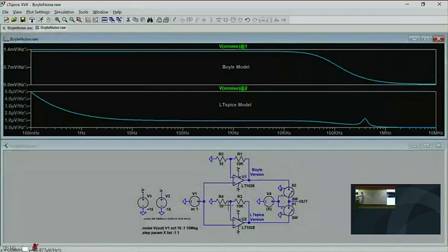So this common mode current is read out to voltage with these things. Now, if Z1 equals Z2, then this common mode current is read out as a common mode voltage, and it's rejected because of the high common mode rejection ratio of the op amp. That's all good. But if Z1 is not equal to Z2, which is probably why you're using an op amp in the first place, then this common mode current is mode mixed to a normal mode signal on the input and it's amplified with the full gain of the op amp. And we include that too.